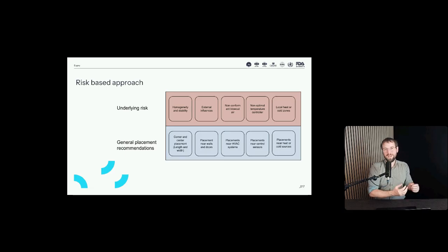If it gets hotter, it will take some time before the heat is transmitted into and conducted into the vial, and therefore changing the temperature. It really depends on how your risk appetite is. If you don't use dampeners and you have these spikes and you write your report, you need to justify that the product temperature did not change as much as the air temperature.